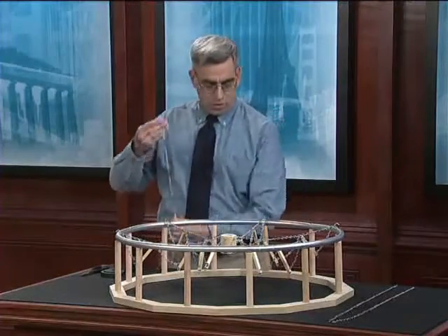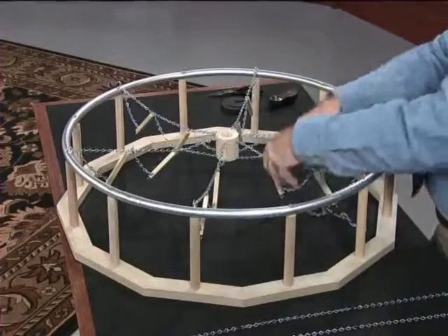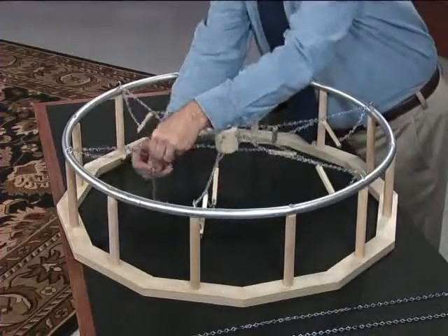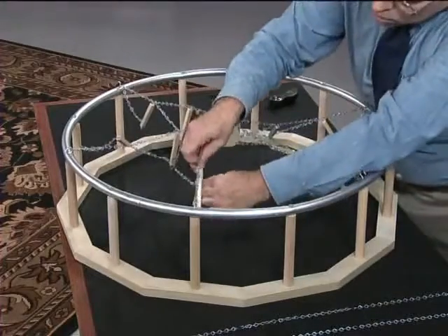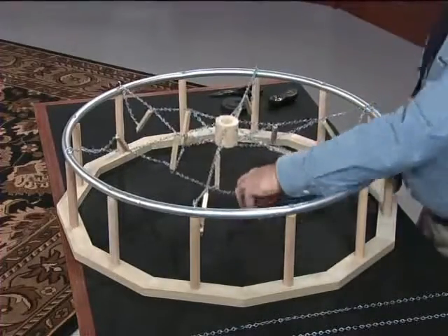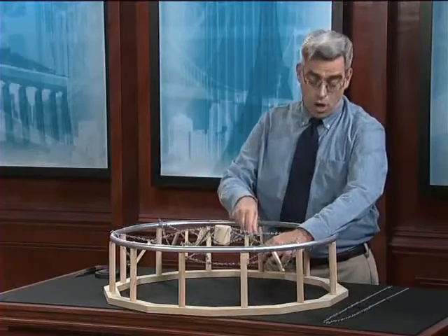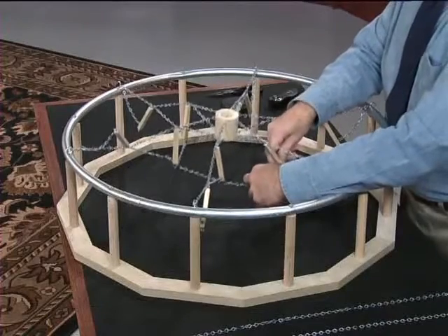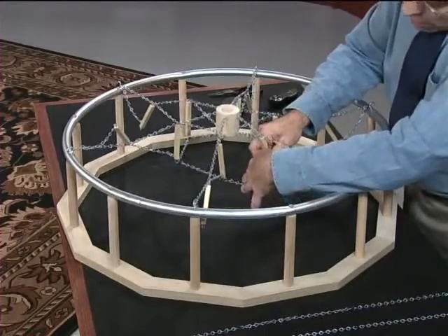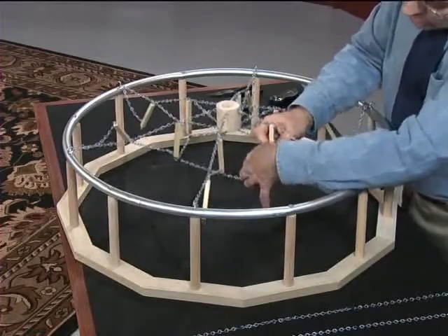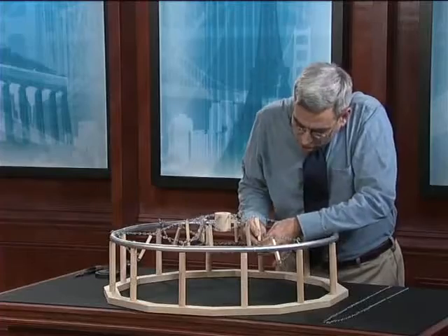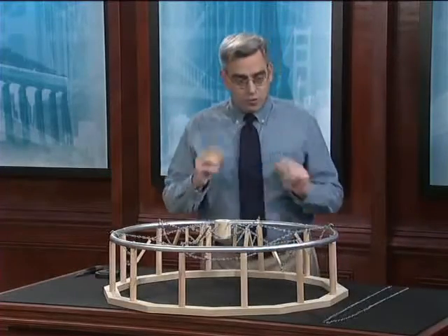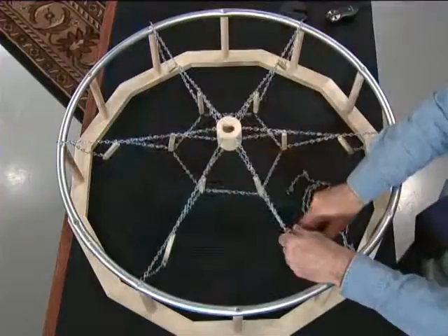So I'm going to attempt to replicate that tension connection. We're going to have to do two of them, so I'll start with the innermost circumferential ring of the cable dome. And now that circumferential ring is almost complete, but I need to make one last connection. And again, watch that as I make the connection, as that circumferential ring is drawn tight, the cable dome itself lifts up in the center. That was the first of two circumferential rings. Now let's do the second.